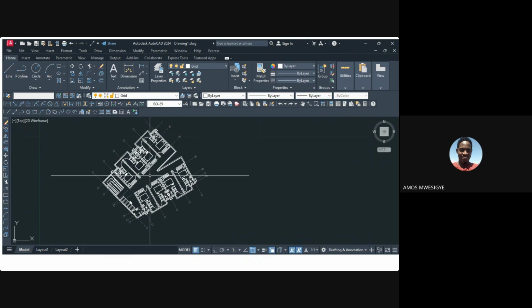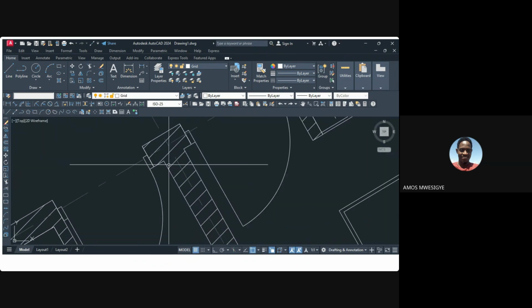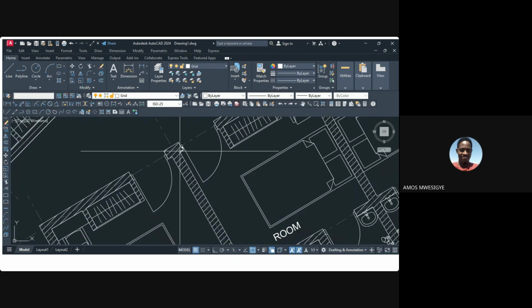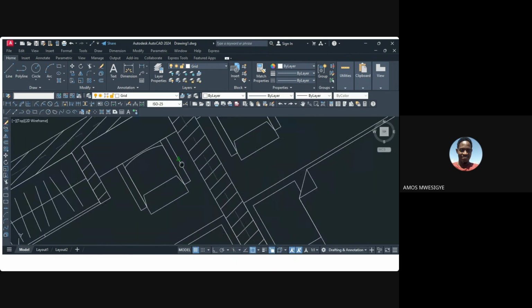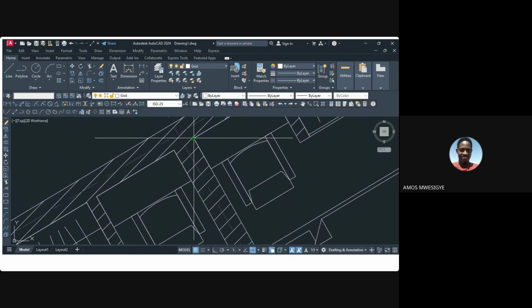Remember from the PDF, the architect gave you the dimension of this wall. Maybe we've measured this. He gave you the real dimensions here, that it is 200 millimeters. So I'm going to really scale this back to that, so that it gives me that measure. So I'm going to first measure the original, as you see. I'm going to measure the original here, which is that.